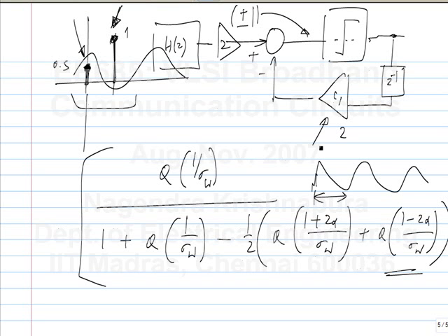So actually in reality, there is no clean way of choosing the number of coefficients for a given channel without doing an extensive number of simulations over the channels that you expect and seeing what the coefficient ranges are and so on. So the number of coefficients as well as the ranges of coefficients are fixed by a lot of, I would say, engineering, by simulations.